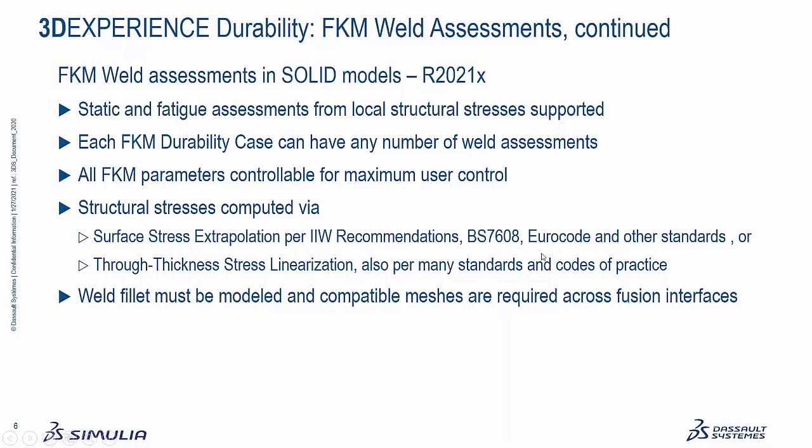Sometimes you can't use surface stress extrapolation if your welds are too close to the edge and there isn't a long enough distance to do extrapolation, or if your welds are too close together, or it's just too close to some other discrete feature, and then you have to switch to through thickness linearization. It's also in most of these standards as an alternative. I've already mentioned that we provide you with maximum controllability of all the FKM parameters.